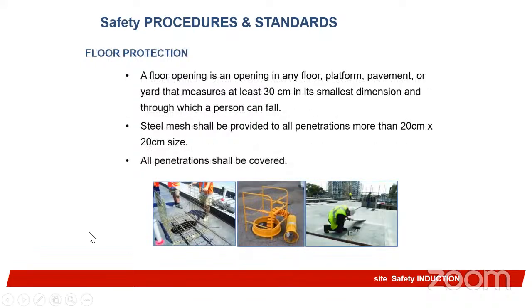The floor protection too is very, very important. A floor opening is an opening in any floor, platform, pavement, or yard that measures at least 3 centimeters in its smallest dimension, that is in diameter, and through which a fall can occur. Any small opening, there must be proper edge protection.